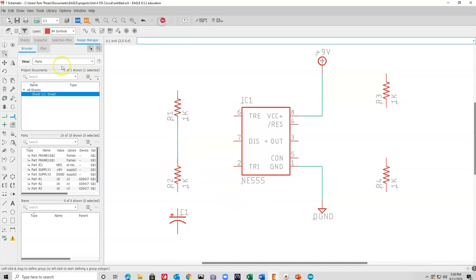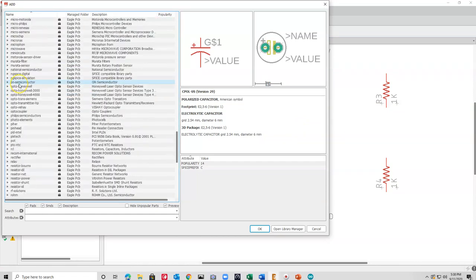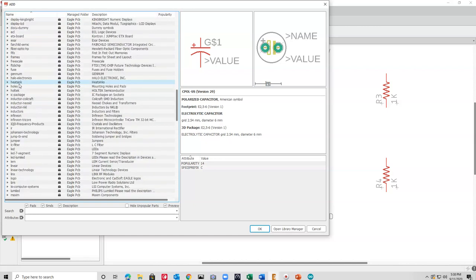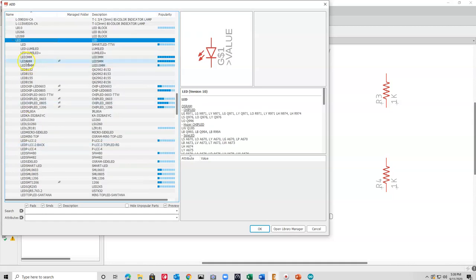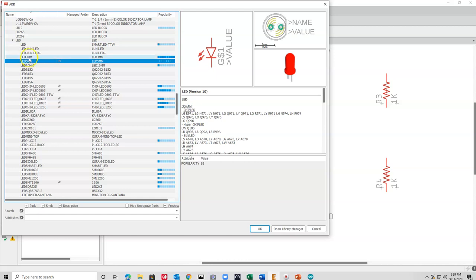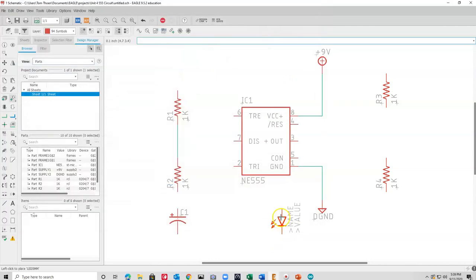And I'm going to hit stop, and then we've got 2 LEDs to add. And if you look at your help sheet, if you go to the LED library, this is kind of a little weird. We're going to go to the LED library, and once again go to the LED library, and we're going to pick the 2 common sizes that we use for through-hole LEDs, 3 millimeter or 5 millimeter. We're going to go with the larger ones, the 5 millimeter. You can see the 3 millimeter are a little bit smaller. It doesn't show an image of it. Okay. And we're going to put one there, and we're going to put one there. And now that concludes all the different components we need, so now we just need to connect everything.